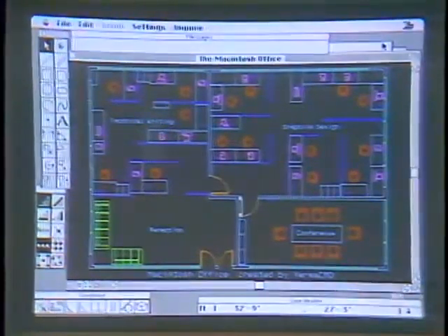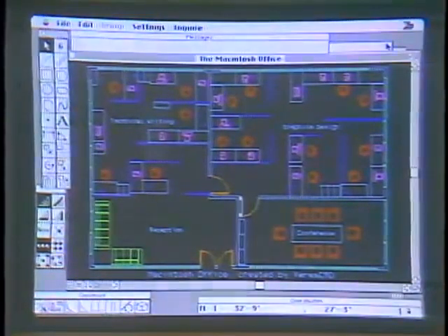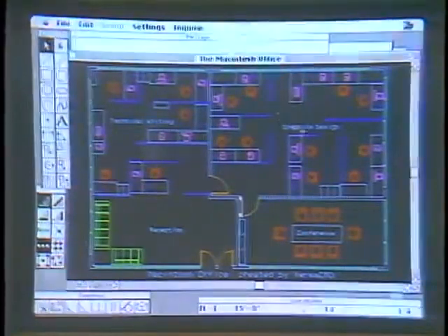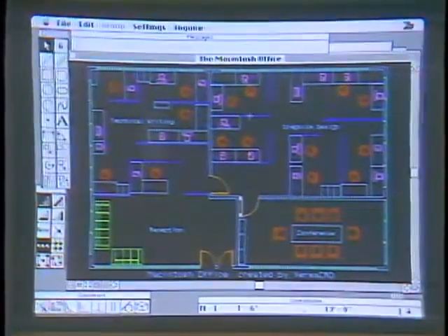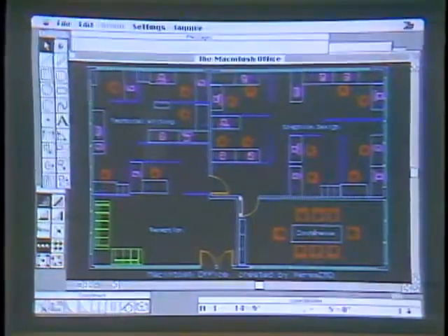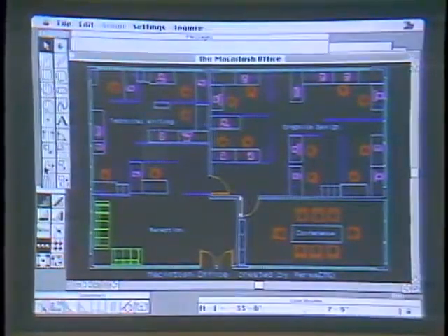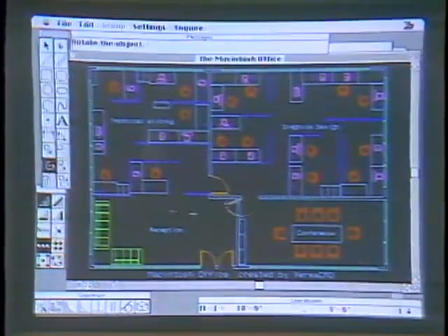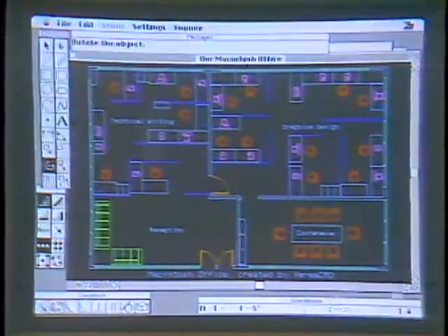You'll notice as you look throughout the drawing, you'll see lots of little computers, desks, and lots of smaller parts of an entire building, which commonly presents an architect or a designer with a problem of tabulating or keeping track of all this. As we go throughout the drawing, there's many ways of working with a given drawing. In this case, I'm simply going to take a door and see if two doors collide. So as I go into the drawing and ask for the rotate command to use, notice that the door can be quickly seen and see. Two doors will be bumping if I put it there. At any given time, I can escape out of my command, so anything you do, you can undo.